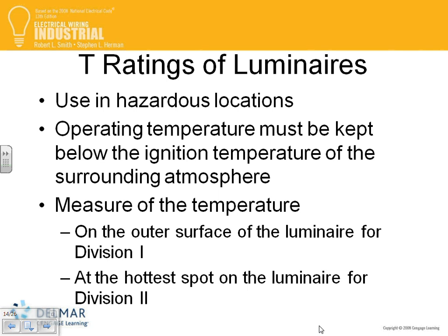Temperature rating of equipment, temperature rating of luminaires, T rating. So what's the T rating? Every luminaire used in a Class 1 Div 1 location will have a stamp on it that tells you the temperature rating of this equipment. There's a really nice page, guys, that has all the temperatures for you. It's page 255. If it has T1, it gives you 842, so the hottest spot is 842. If the gas needs 500 to ignite, I wouldn't put a fixture that will get 842 hot in an area where 500 ignites the gas.